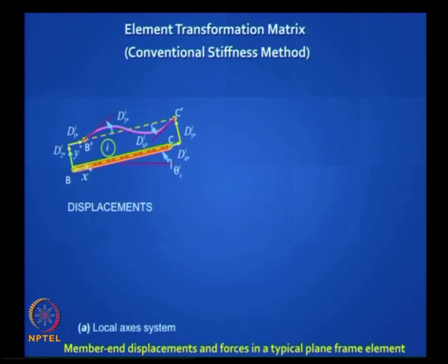This is what we did in the last class, right? Here you have 1 star, 2 star, 3 star and so on, 1 star, 2 star here for sure. If this joint has moved here, the displacement along the local x axis is d1 star, right, with the i standing for the ith element, and this movement normal to it is d2 star, is it clear?